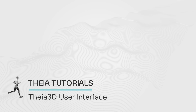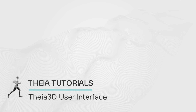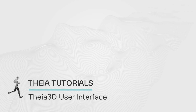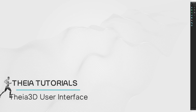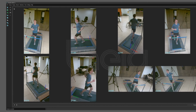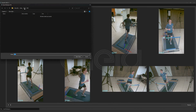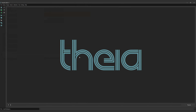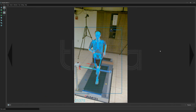In this video, we will describe the layout of the Theia3D application user interface and where its many functions are located. The main portion of the application window is the 2D view area, where 2D camera views are displayed once loaded. With data loaded, the top frame of the application window will display the path for the loaded data and calibration file. If you have analyzed the loaded data or loaded and analyzed the Theia3D workspace, the 3D scene is projected onto each view. If all views cannot fit in the available area due to the number of cameras, arrows are shown and can be used to move through the available views.